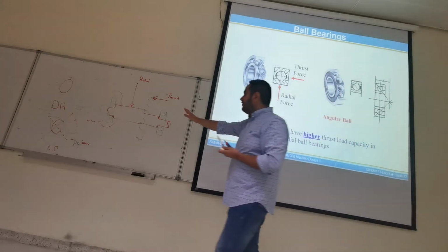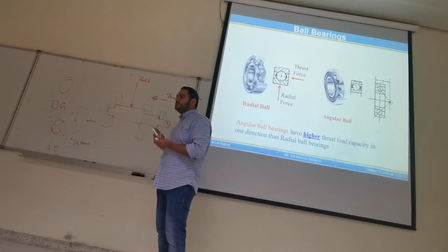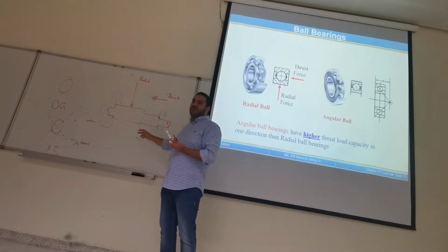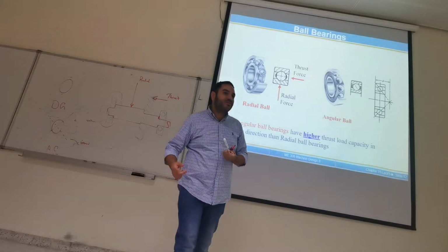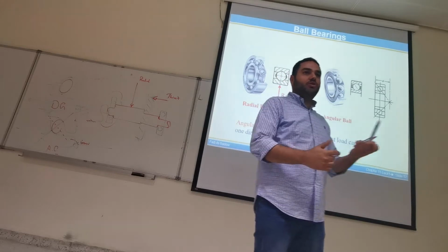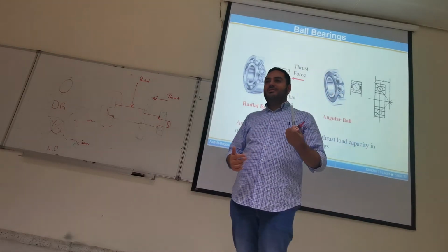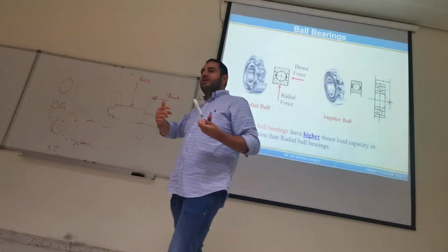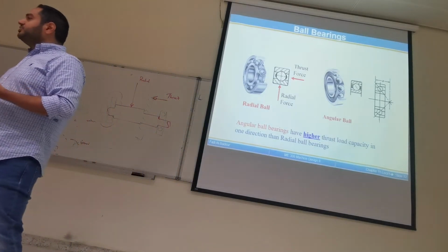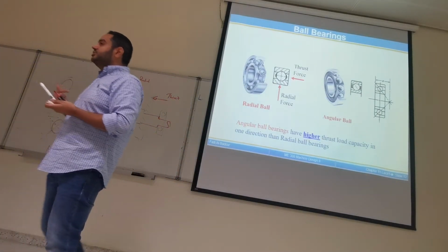Like for example, if I have a helical gear, this exact example. If the helical gear is running clockwise, it's different than when it runs counterclockwise. Imagine you have motion in both directions. One time you make the gear run clockwise, and the second time counterclockwise. So the direction of the thrust force will change.